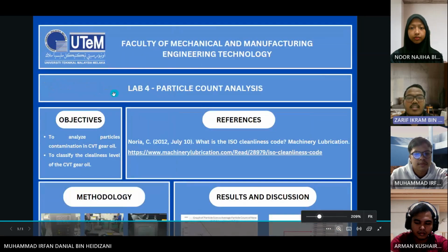The importance of clean oil cannot be ignored in any machinery system. Any machine component that experiences contact and friction will generate wear debris regardless of the existence of lubricants. Particle count data is an invaluable part of a predictive condition monitoring program. Particle count data can be used to ensure that component wear is at a minimum and to determine if hydraulic fluid is clean enough for reliable operation.